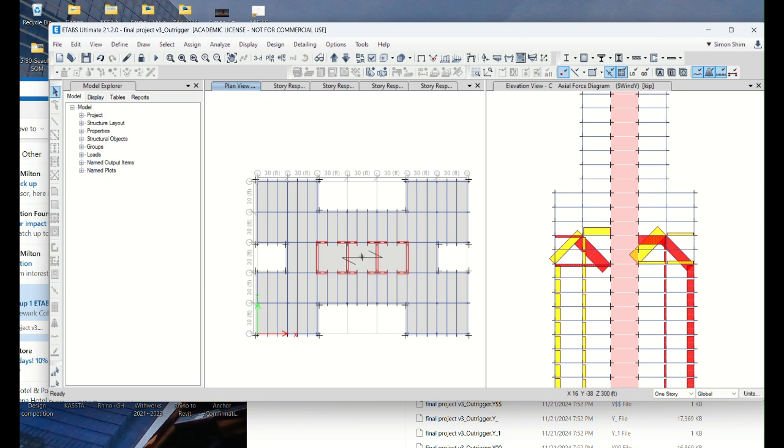Obviously, we need miscellaneous beams here, especially along the perimeter. This column is okay because it is braced by this beam. But this beam doesn't have a bracing point, so typically for this type of beam we have two small beams like this. You don't have to model those beams here. Those are secondary beams for bracing purposes, for torsion.